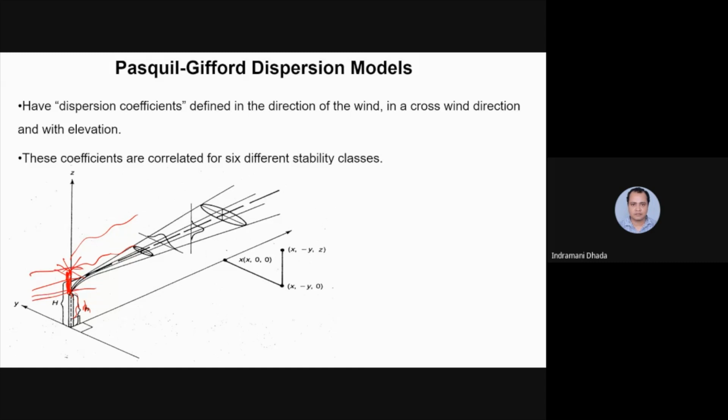So the height till which it will not spread is called the escape height. Small h is the chimney height, and considering the escape height and this chimney height, we can say the total, gross height is capital H. Beyond capital H the plume starts spreading.